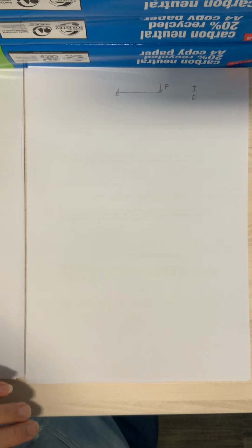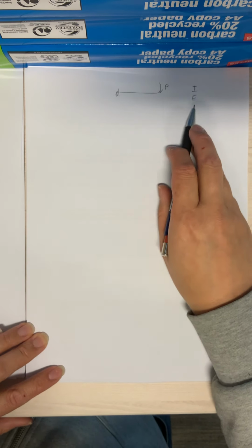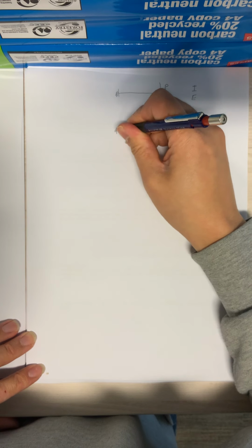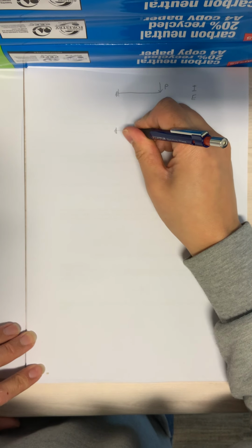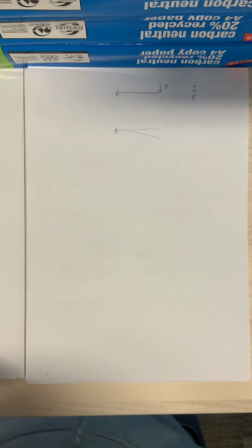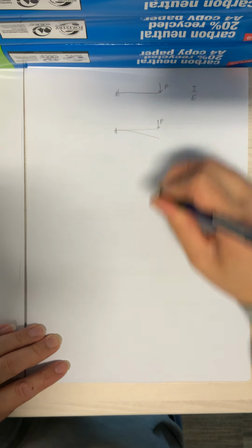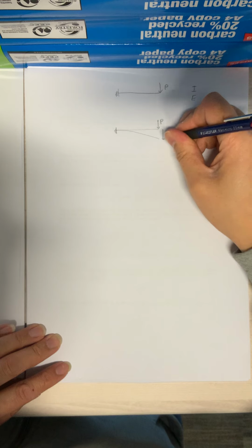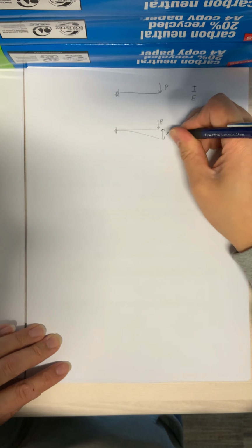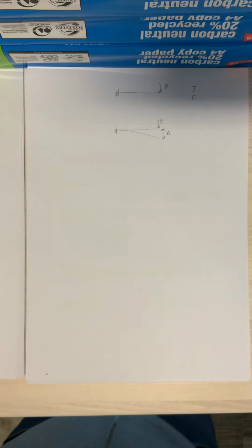So E would of course be the Young's modulus. So the bending stiffness of this member here is going to be E multiplied by I. So let's keep it real. So this is the real system. The real system would have a deflection like that. So originally you've got this load P, and it's going to have moved by a distance delta. Okay, and we want to calculate what delta is.